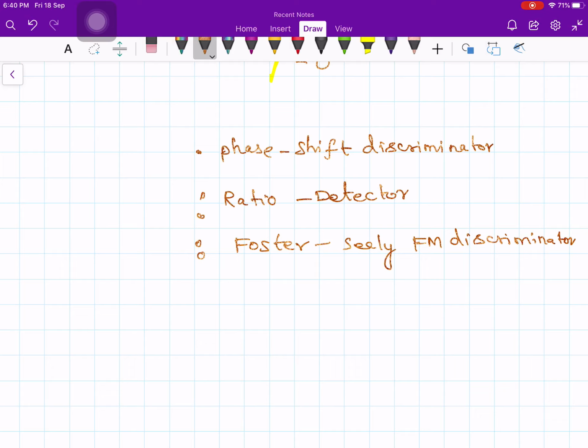Conceptually, we have discussed it now; let us look at it quantitatively. We are really using only the linear portion of the bandpass filter. Only the linear portion we are interested in. In the linear region, we are trying to utilize it and get back our message signal from the frequency modulated signal.